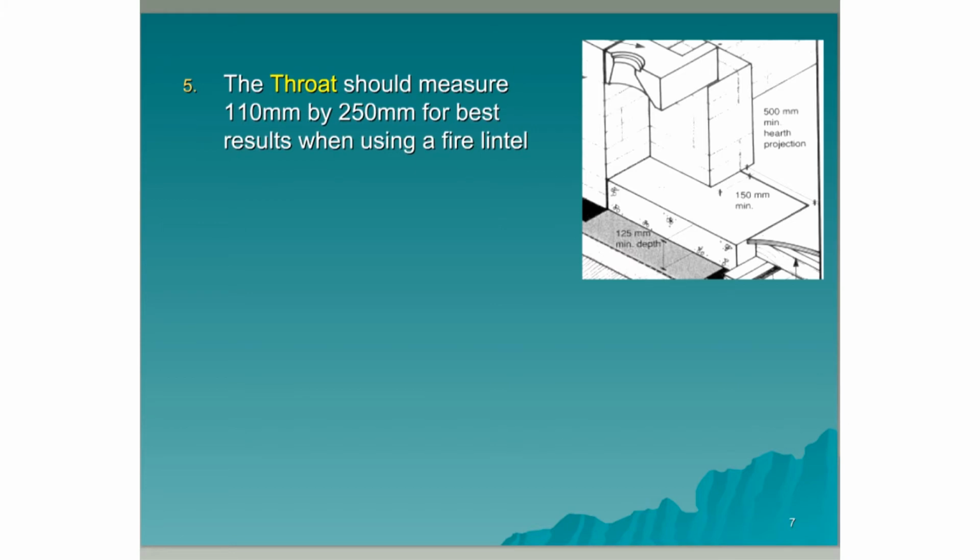The throat should measure 110 mm by 250 mm for best results when using a fire lintel. This is the throat.